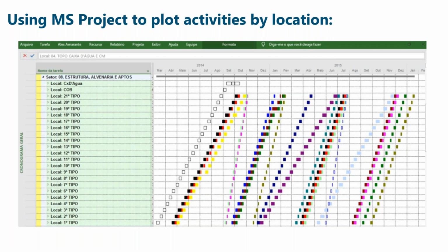So what people usually do with a linear schedule is develop summary activities to show how the work is grouped and how things move over time. Our tool, Graphic Schedule, uses the activity ID to define the start date and one more activity ID to define the finish date of whatever shape you want to draw. So if you have a line that moves along your project, you would pick one ID to start the line and another ID to finish the line, and then the shape is now linked to those activity IDs so that if the schedule changes, the dates will update automatically.